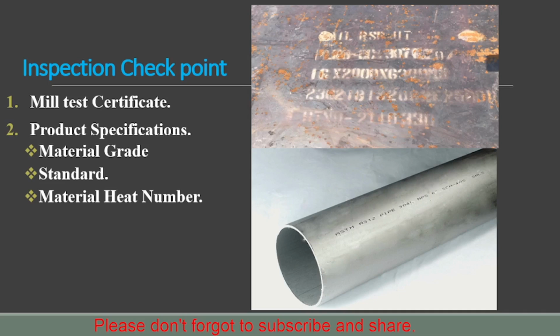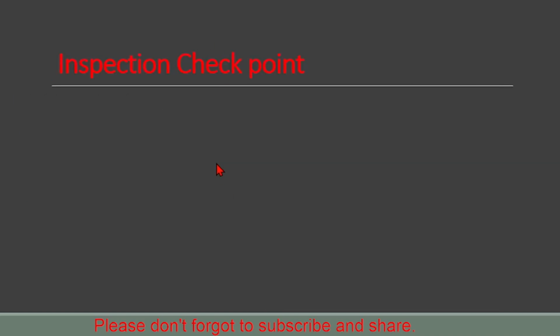I hope when you go for the inspection, you can see this type of writing. There we need to identify the material grade, what material this is, what the standard is, and what the heat number is. These three things we have to comply with our mill test certificate information. Then we will be able to track that this material certificate is for this material. I hope you understand what I mean. Okay, next slide, let's see what we have.